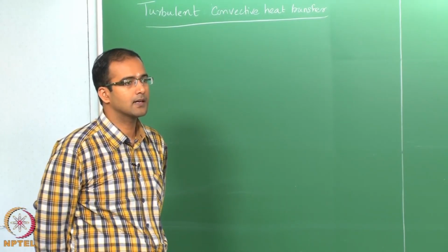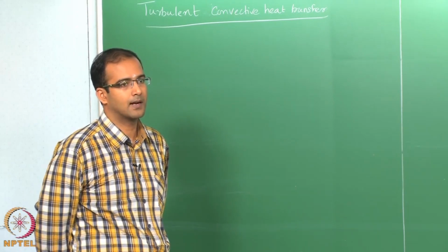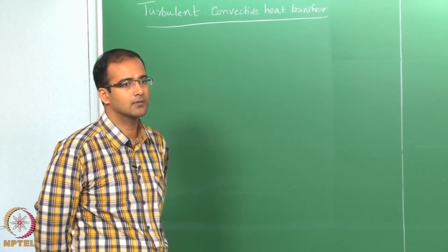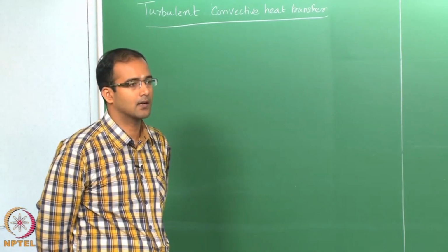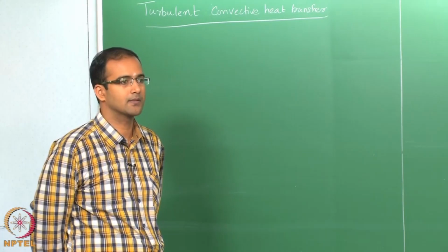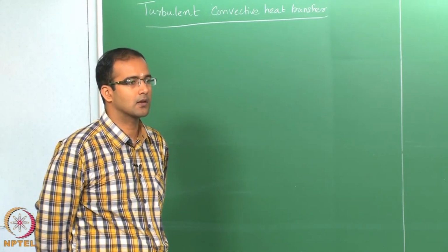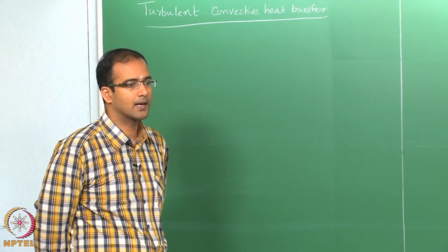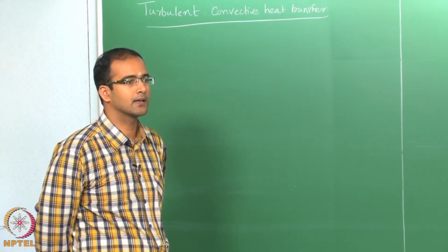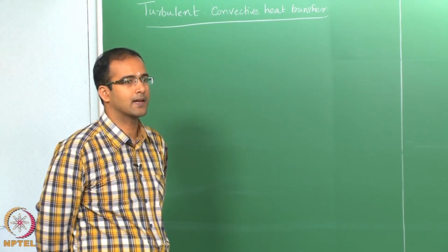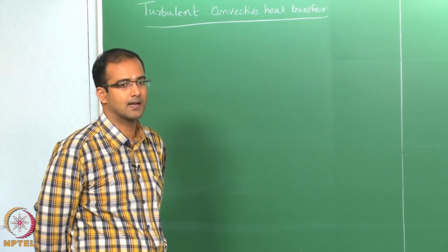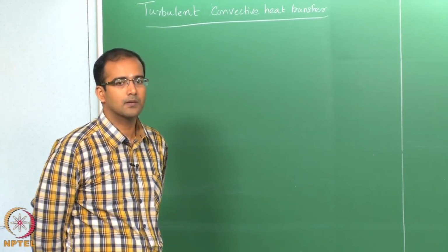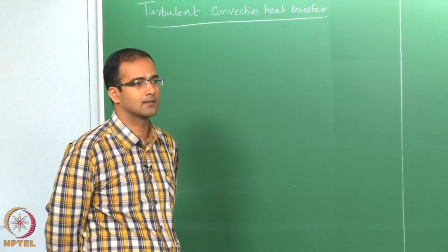So, to start with, the simplistic kind of arguments in turbulent heat transfer state that we can use certain analogies like the Reynolds analogy. We can extend these analogies to turbulent flows also. They give reasonable accuracy, and in very little time you can get a good prediction of the local Nusselt numbers and things like that, without having to solve them rigorously using computational methods.